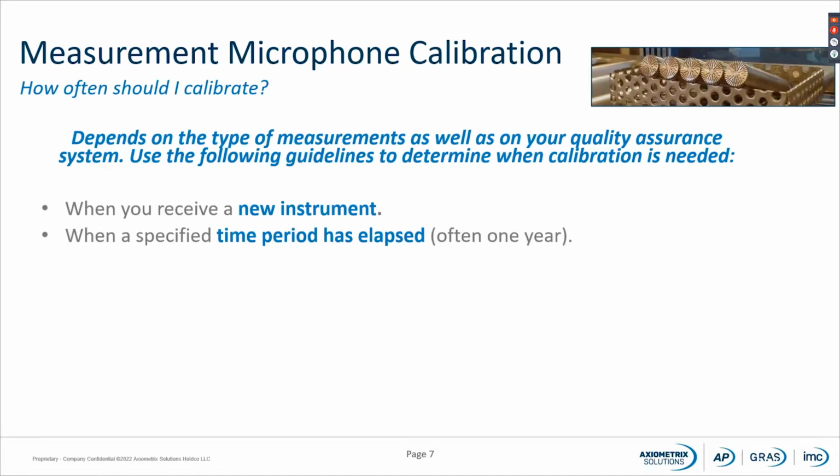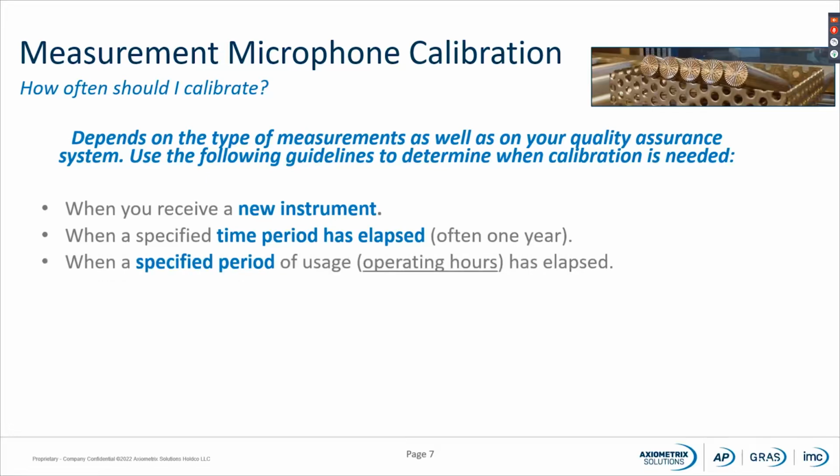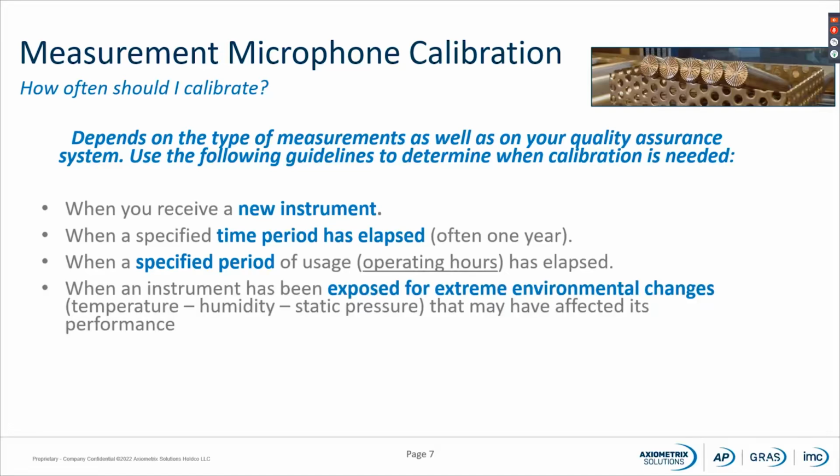When a specific time period has elapsed, often one year, it could be a good idea to perform a new calibration of your equipment. When a specified period of usage, operation hours, has elapsed, it could be a good idea to do a calibration.